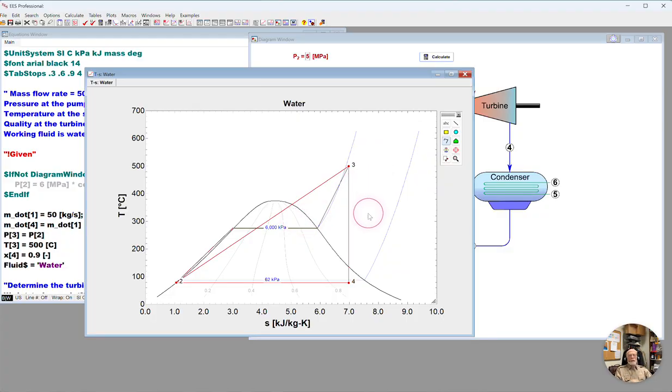So, in order to do that, we have to add a couple of extra state points. We'll add one here where it changes from a subcooled liquid to a saturated liquid. So we know the pressure and we know quality is 0. Here we know the pressure, quality of 1. And then this will become state point 5, state point 6, and it will come back across. So we will do that, and we will also create some code that will automatically draw these based upon what we program.